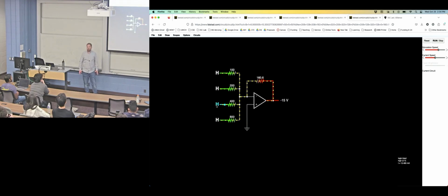I see confusion. I see terror. This is analog. So what do you have to actually learn about this one? There's a magical thing called a summing amplifier. It works in some way. Who knows? Doesn't matter. You have some binary values that come in that are selecting some amount of current that goes through. It's the value of those resistors, right? You're summing effectively the current that goes through a 100 ohm resistor, there's a lot, and the current that goes through 200, the 400, and the 800. And those are all different proportions. And so now I'm going to connect a lot of current, a little bit of current, a little bit of other current, and the binary combination of those will give me a proportional analog output.